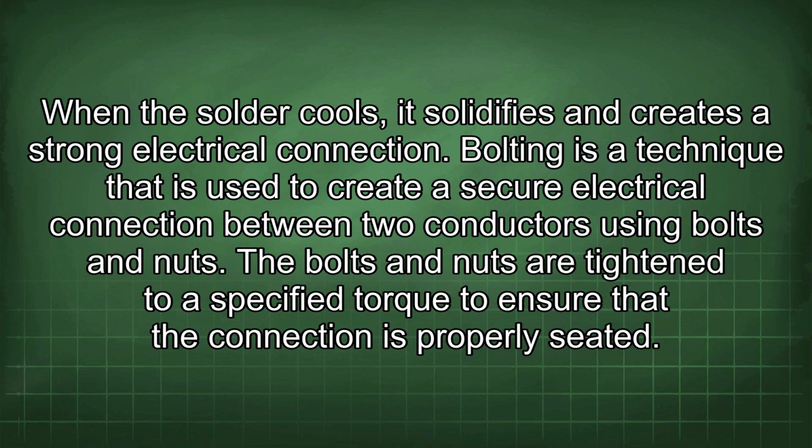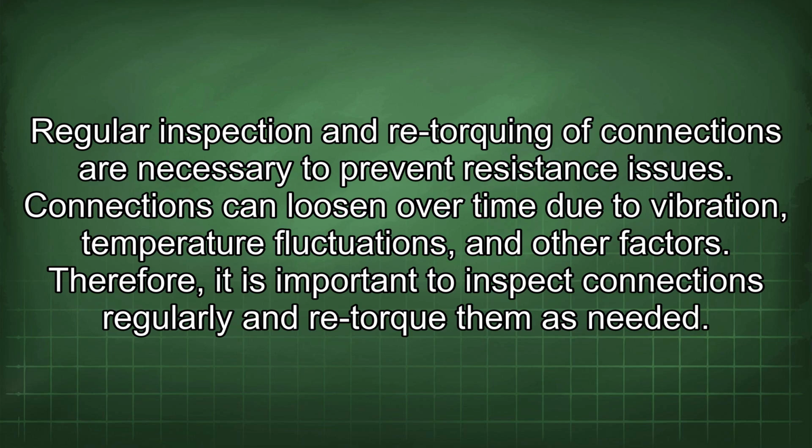Bolting is a technique that is used to create a secure electrical connection between two conductors using bolts and nuts. The bolts and nuts are tightened to a specified torque to ensure that the connection is properly seated. Regular inspection and retorquing of connections are necessary to prevent resistance issues.